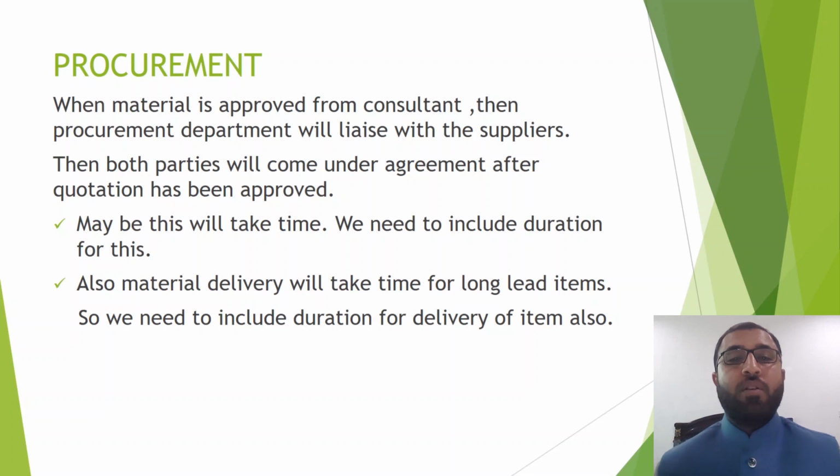Then your engineer, like the project manager and your site engineer, will raise a requisition for that material. That requisition will go to your procurement department. Then your procurement department will liaise with the supplier of that material. To get into a contract with them, maybe some accounts department will also be involved, so it will take some time. So all this time is considered as procurement time. Then they need to procure that material. I already told you some materials are long lead, some are non-long lead, so it will take some time.